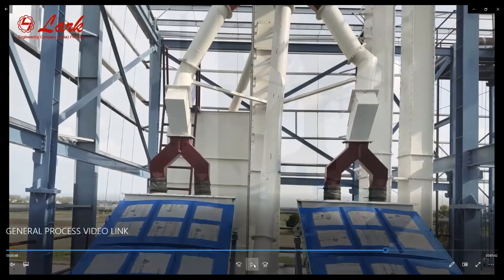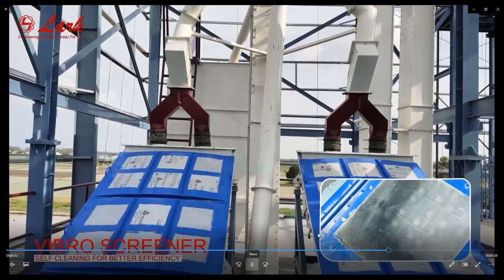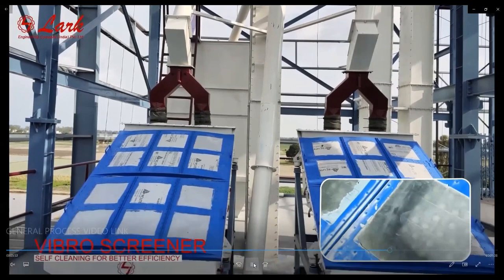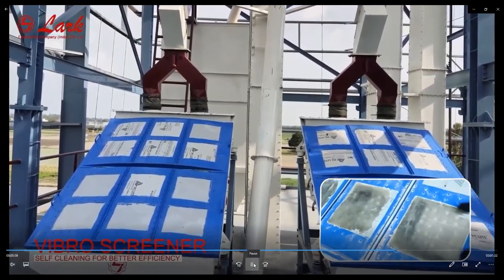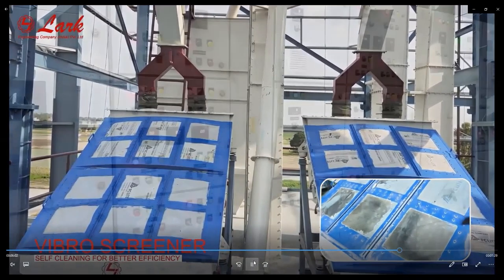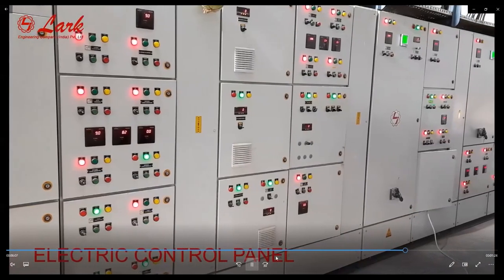So auto cleaning screens help. You can see the vibrating rubber balls are there to clean the screen automatically, so that they can work at 90 or 95% efficiency. In general, with less cleaning, the screens only work at 40 to 50% efficiency after 1 hour.